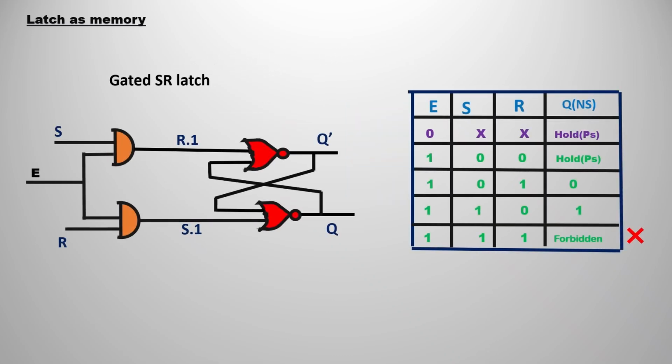We have already seen what is inside the block of the SR latch, meaning the transparent latch. Simply replace the transparent latch with what we have already shown. After replacement, this is the circuit diagram that we are going to formulate, because we have just added AND gates with the enable line. So in total we have 3 inputs here: R, S and E.